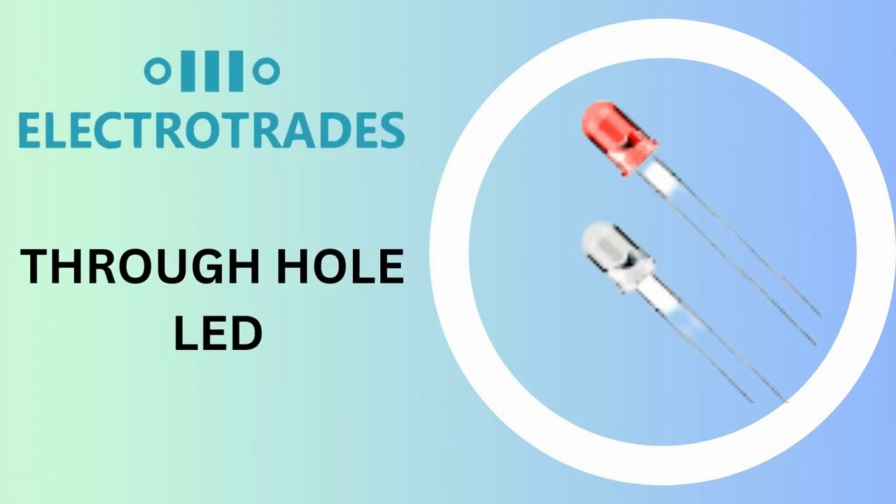Reverse bias. When a negative voltage is applied to the P-type region and a positive voltage to the N-type region, the potential barrier increases, inhibiting the flow of current across the junction. This is called reverse bias, and the diode becomes non-conductive, acting as an insulator.